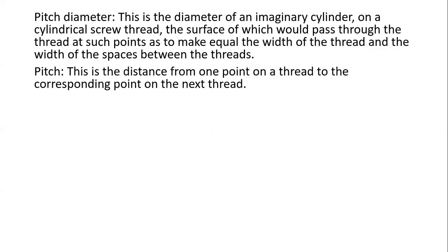But then, this is the one that makes it complete, the pitch. So the pitch, you're looking at a thread at one point, you identify maybe it's the crest. The distance from that point to the next corresponding point along the axis on the next thread, that is our pitch.